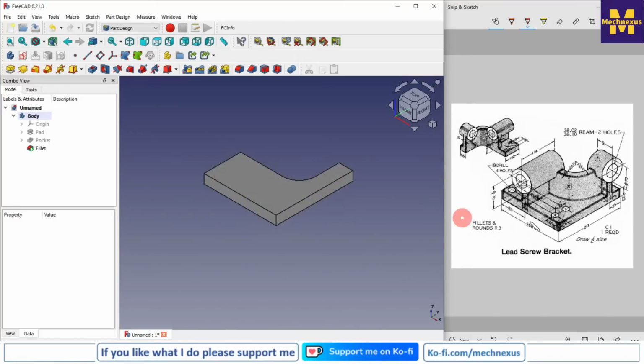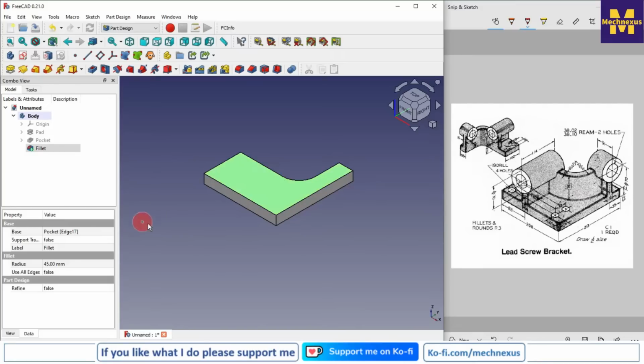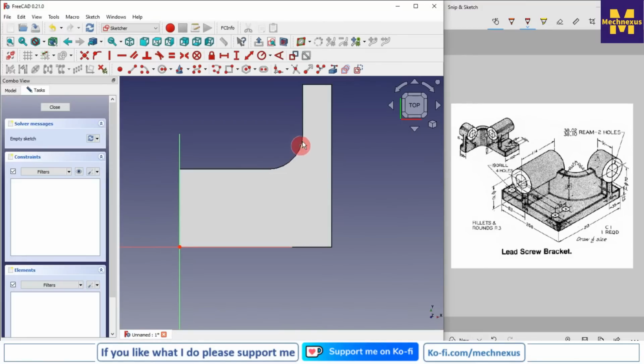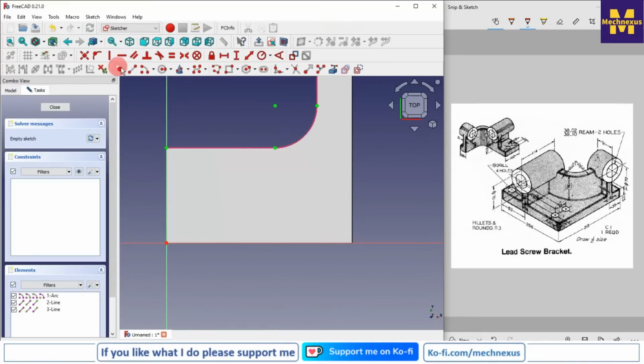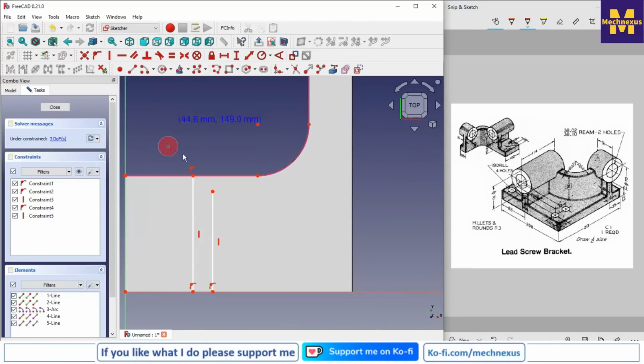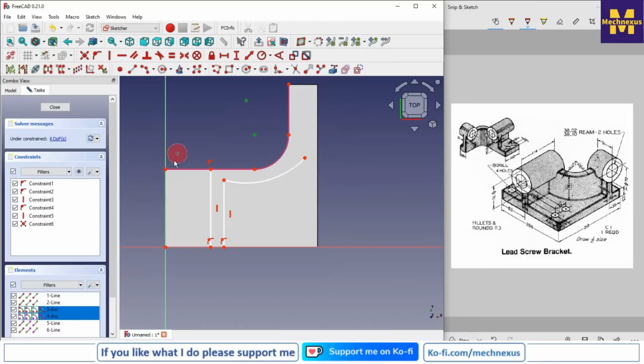Now we will create this profile. So for this I will select the face and create a sketch, and now I will project this geometry, this also and this also, and now I select the line, again select the line, and now I will select the 3-point arc and I will make it merge.